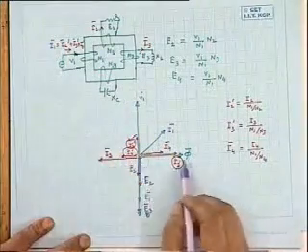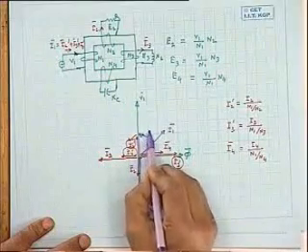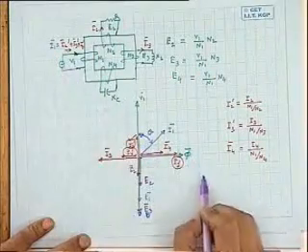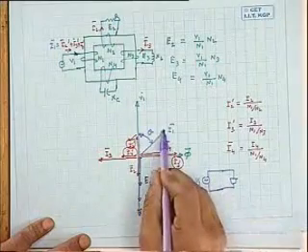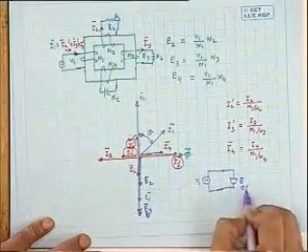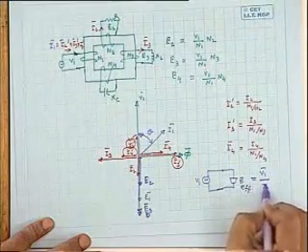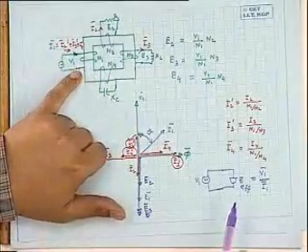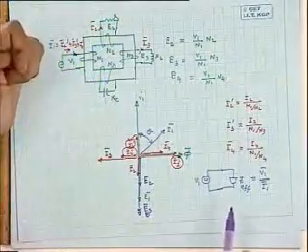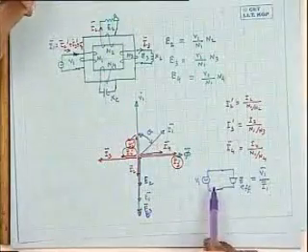Is not this I can find out to the source, and I will find out what is the resultant power factor at which it is supplying this. So to the source V1, what impedance is connected? V1 divided by I1 bar, that is the effective impedance as if connected across the load, V1 bar by I1 bar. Or in other words, across the supply, if you connect this transformer, with various loads connected across its secondary, the supply will react in some way by drawing some current I1 at some power factor angle theta. The same thing will happen if you have this supply and connect it across a load whose impedance is Z effective. The supply will not distinguish between these two things.